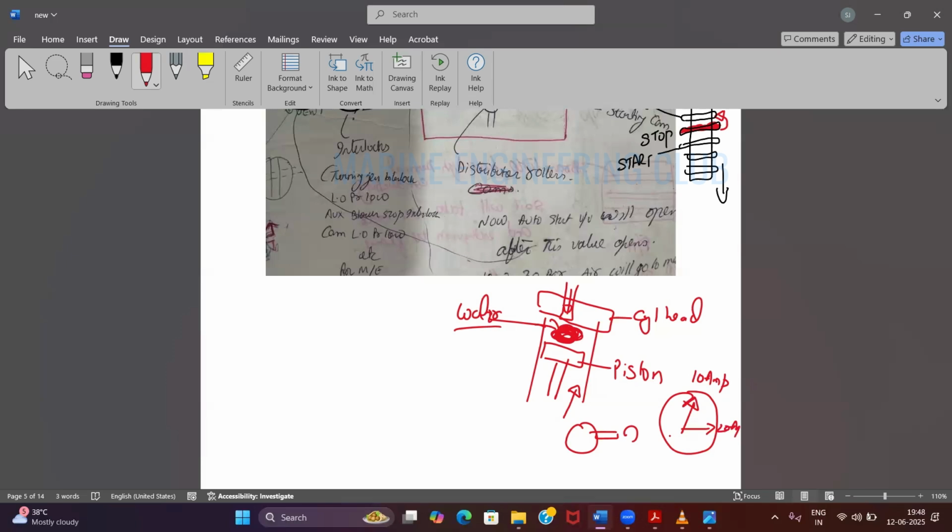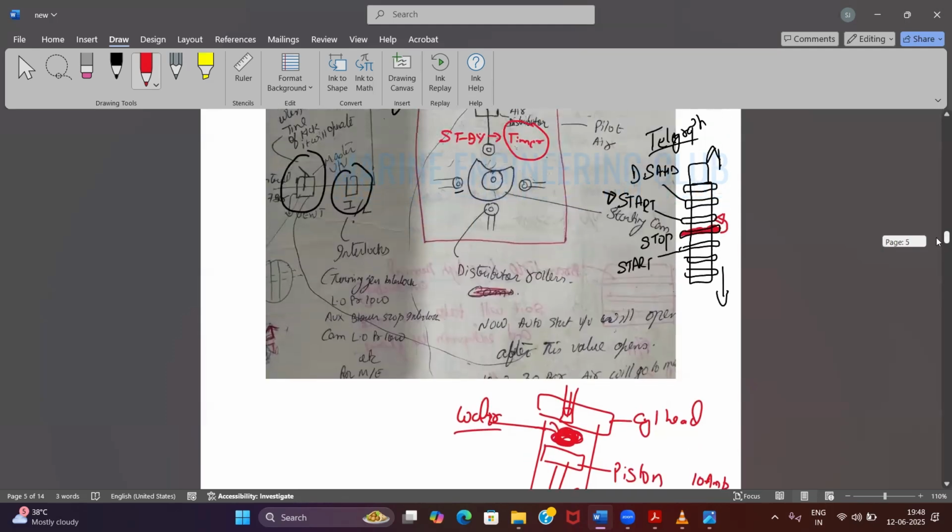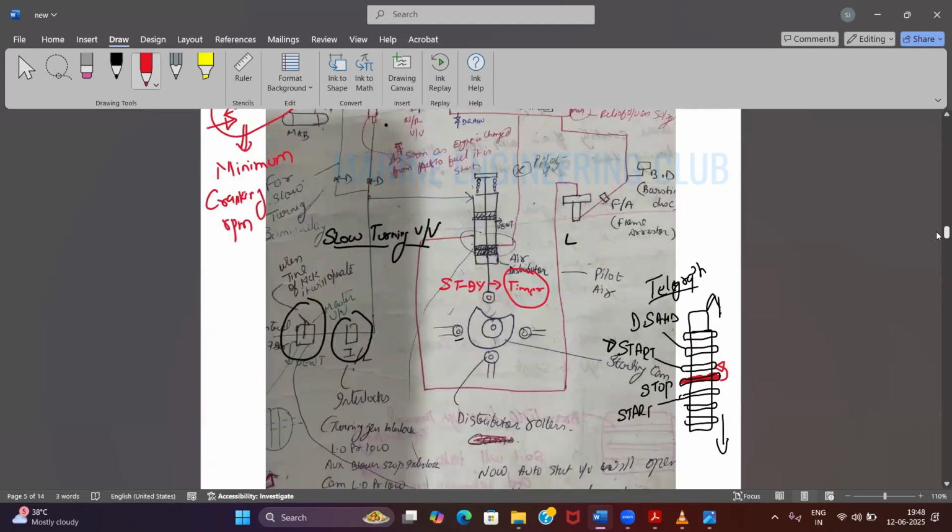That's why 2 hours notice has been given to you, to make you understand whether everything is okay or not. If not, you have a little bit of time to correct it. Obviously, if water is coming into my piston from the liner or the cylinder head, from wherever, I can ask for more port stay and go for the repairs. But if I suddenly give 30 bar air, then gone. Everything is damaged. Agreed?